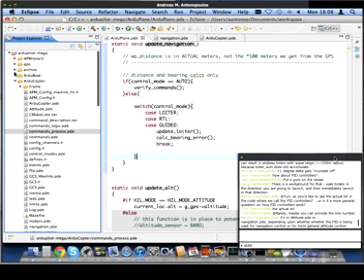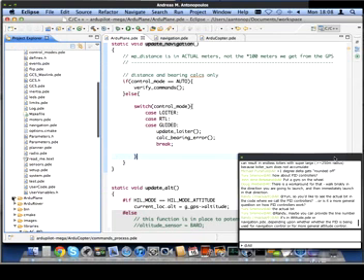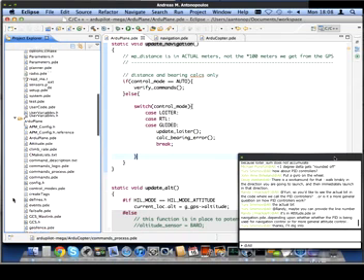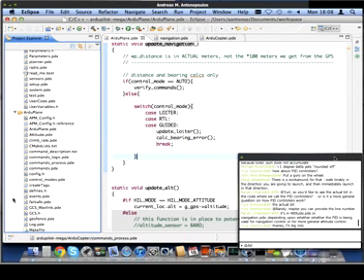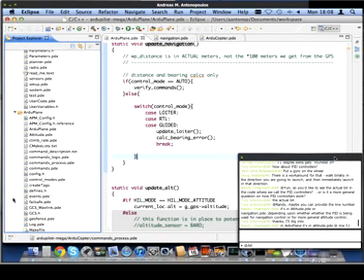So you have to rely on the fact that it will set a very low throttle, and then you may want a separate throttle cut on your transmitter, or you may want a servo set operation in your mission that sets a particular servo to cut the throttle completely, to disable the ignition on a nitro or petrol plane.